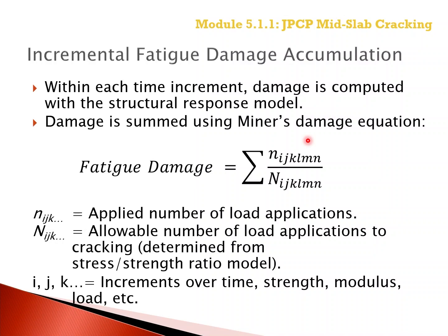The damage is calculated based on the critical responses, tensile stress, computed by the artificial neural networks developed from the ISLAB 2000 finite element program. Tensile stress is calculated at the top and bottom of the PCC slab at different critical locations based on the axle load geometry within the time increment of the time of day.